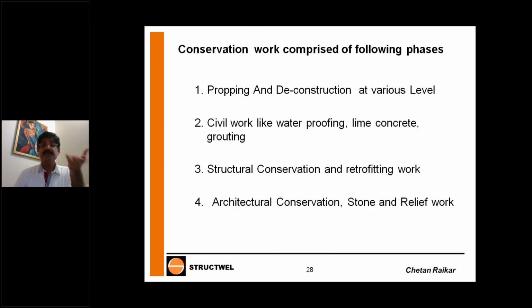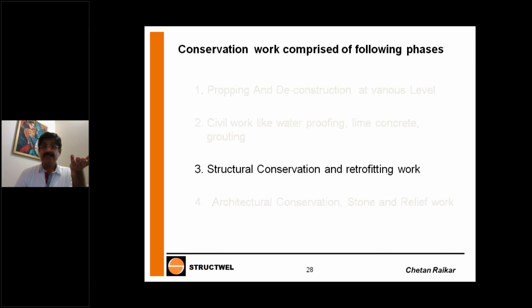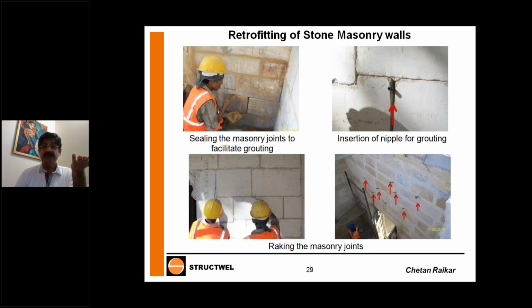This is purely a civil engineering, structural engineering job, what I have shown you till then. Now let us go to structural conservation and retrofitting work. You have seen the cracking to the walls, right? How did we repair those cracks? In some cases we even pushed the structure back, reduced the width of the cracking. All the cracks were sealed, they were grouted.